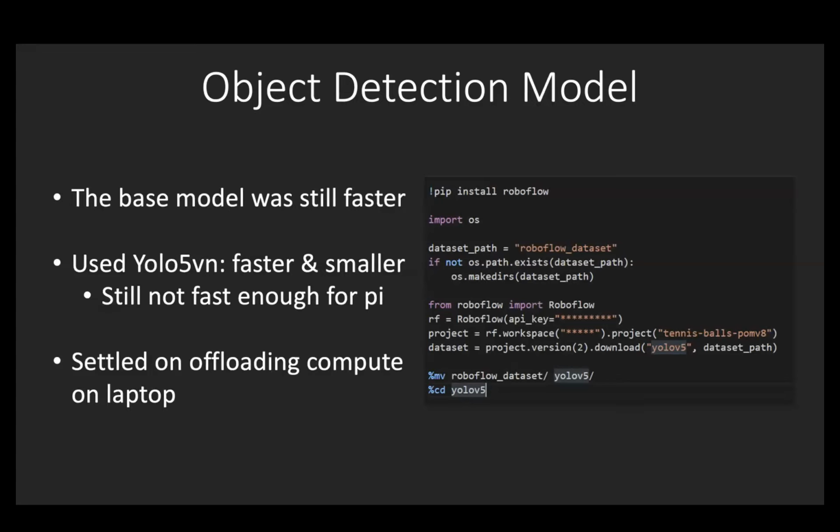and it cannot run on the popper because of the Raspberry Pi performance limitation. So we had to offload that to a computer so we can have good performance in terms of detection. And the popper would send the image, and we'd do the inference, offload the inference, and send back the position of that ball if detected, right?